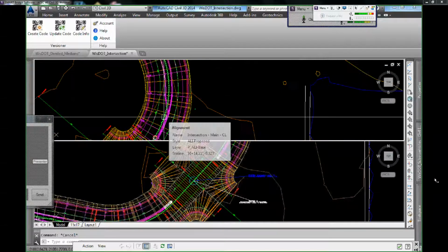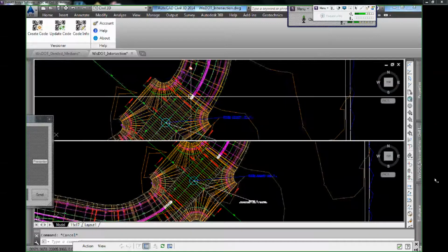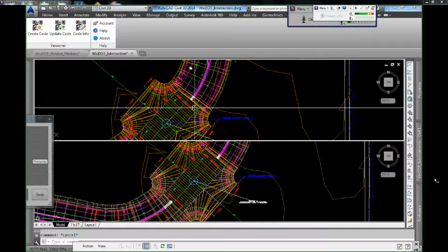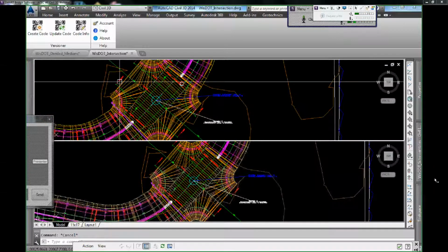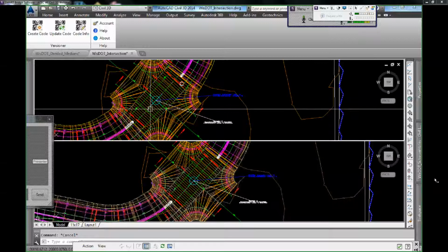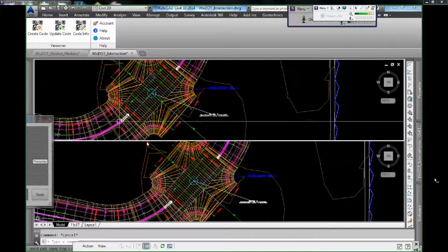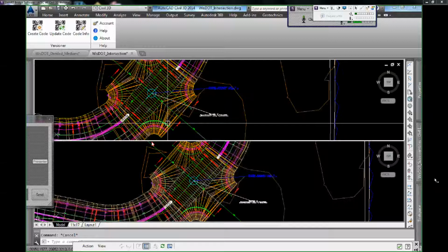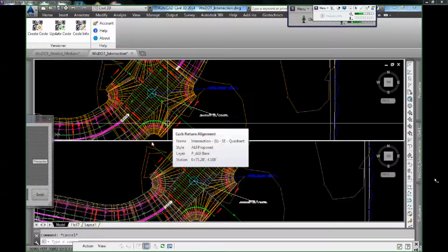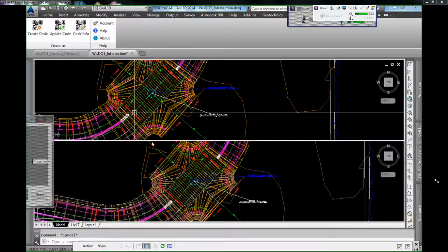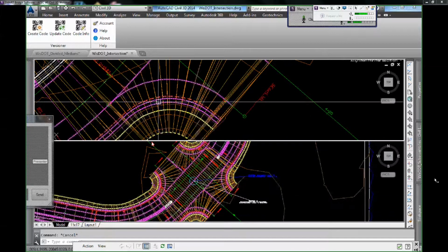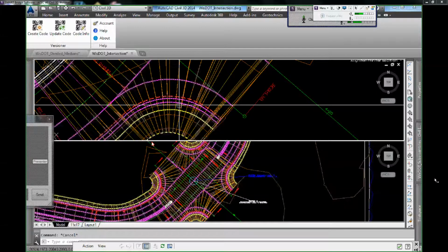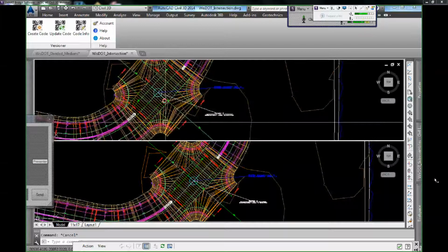Now we probably all know that Civil 3D does not do bullnoses very well or very easy, and there is no way of really automating this process within this intersection. Okay, so actually what I've got going on here, I've used the intersection tool to build this portion of it, and this is just using stock assemblies here, nothing really special. If I was going to 3D and look at this, this is just the standard shoulder, I believe, over here. Nothing special. I mean, this takes literally, what, a minute and a half to create.